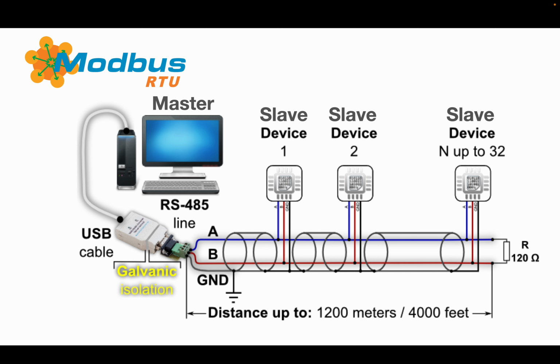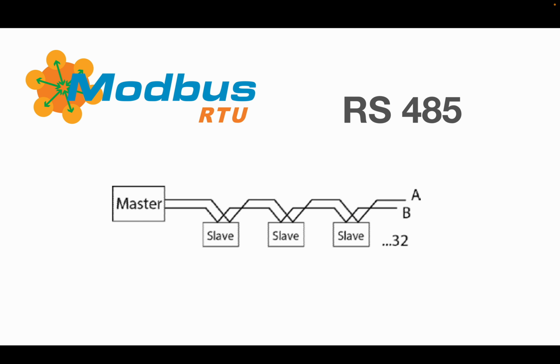So there's a certain limitation, because as one device is sending, there's a number of devices listening, and the listening devices are obviously all drawing current. So there's a limit to how many we can have out of one sender. If we need to have more, we can extend that, but we just need something on the side which is boosting the signal. Let's have a quick look at the simplified version of it.